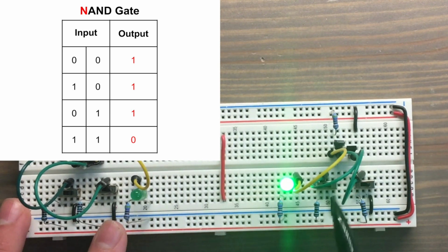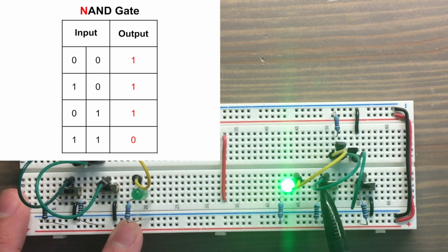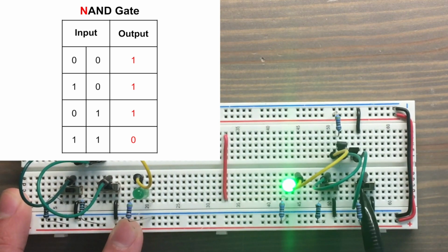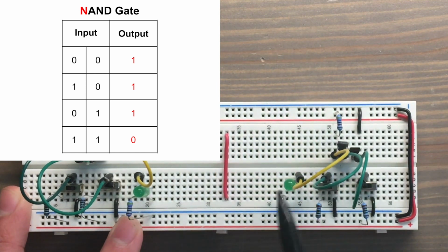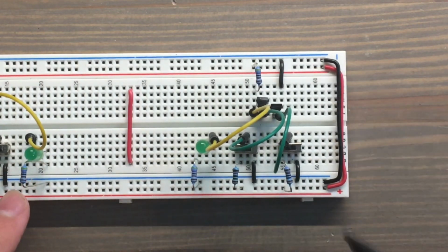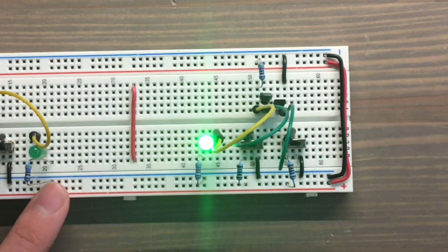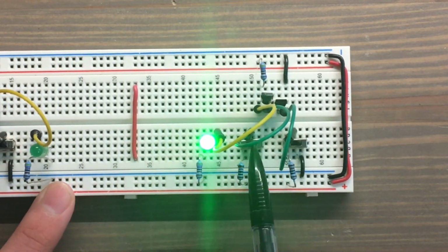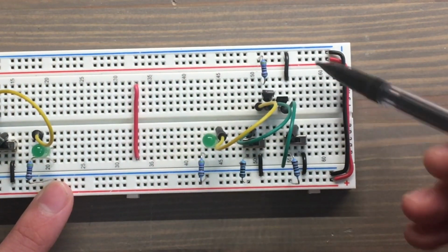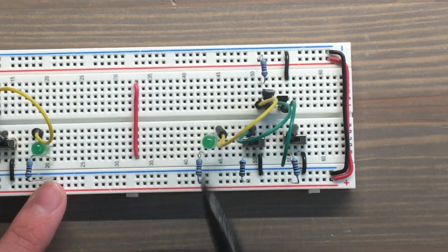So you can see right now when these are both off, the light's on. And if one of them is on, the output will stay on. But if we turn both of them on, the light turns off. And this works similar to how our inverter works. When these switches are both off, power just goes through this resistor and through the LED. But when both of these are on, allowing power through the transistors, the easiest path is to just go through this wire to ground without going through the LED. So now we will move on to the